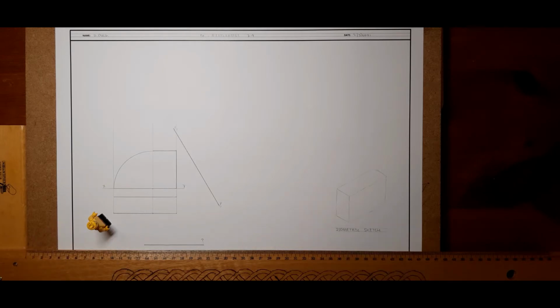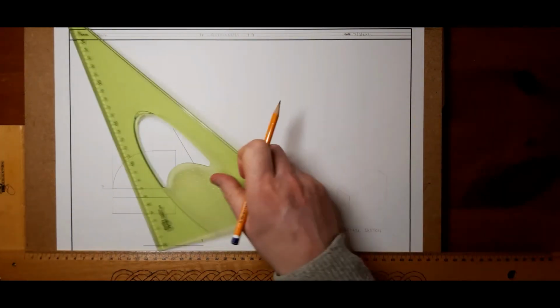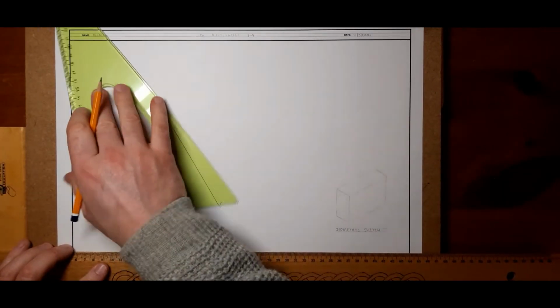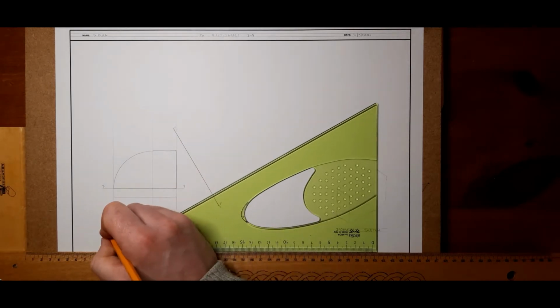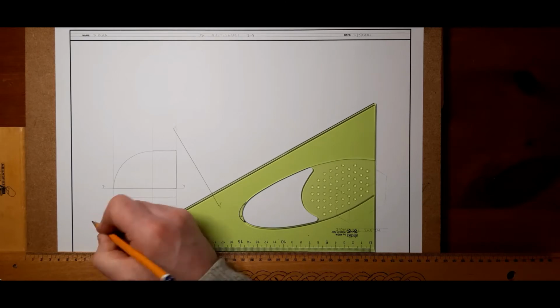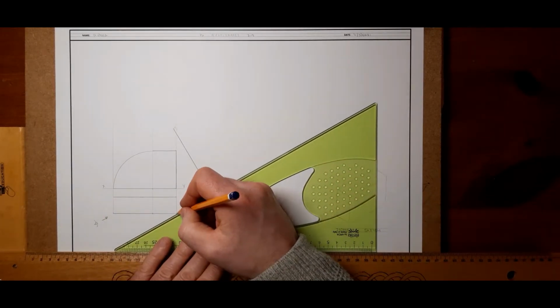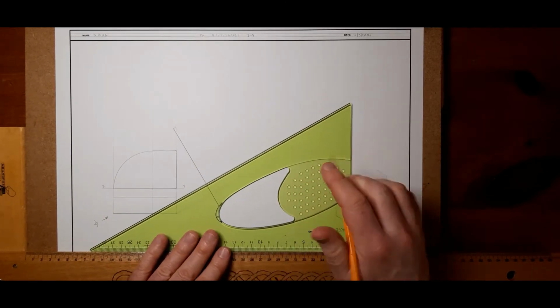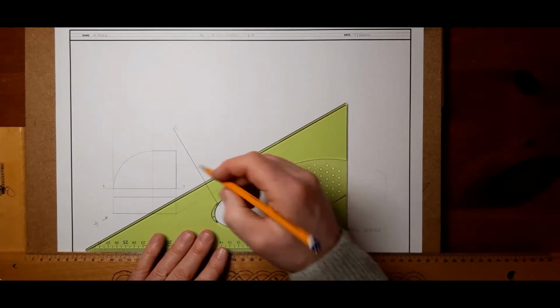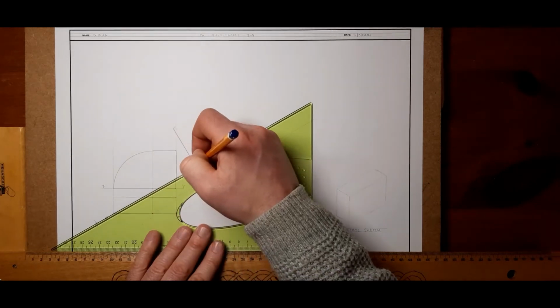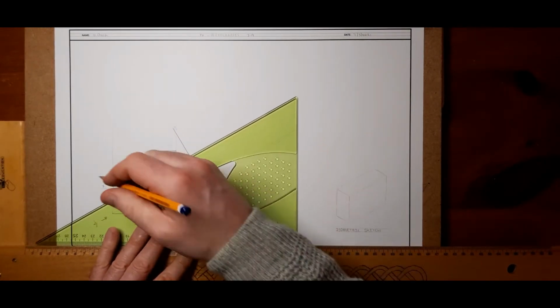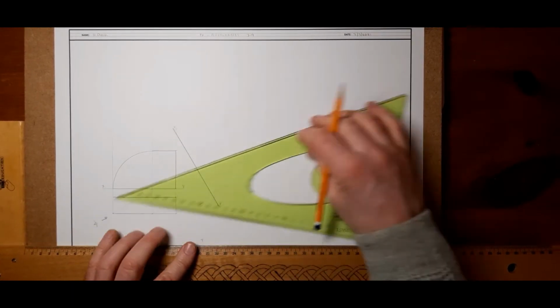But I'm going to go ahead now and process this. So the question is very nicely set up. It's at 60 degrees there. So that means when we flip here, we're viewing in at 90 degrees to that X1, Y1 line. And that means all our projection lines will be at 30 degrees. So you can run up all the points of interest that we have so far. Be on the ground. That one will also be on the ground.